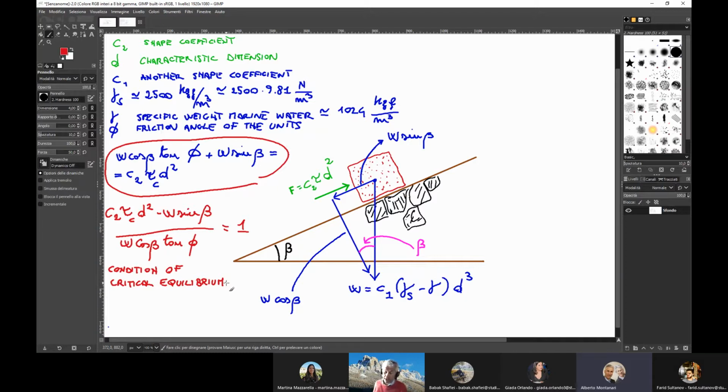And look, we gained a physical understanding of how the process works. You may ask, what happens when I have the rundown? When you have the rundown, the situation is very similar. You just have to change the sign of the green forcing F. Then you have two destabilizing forces, because the self-weight in the direction parallel to the slope becomes a destabilizing force.